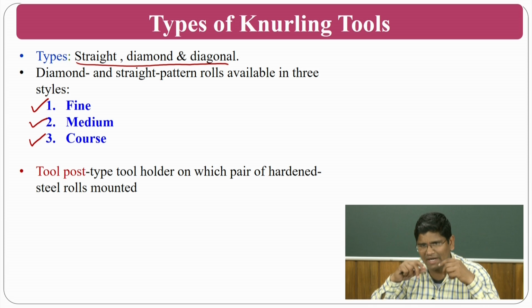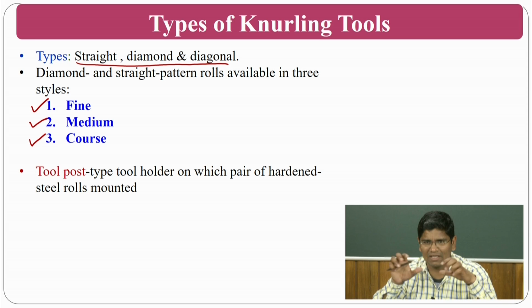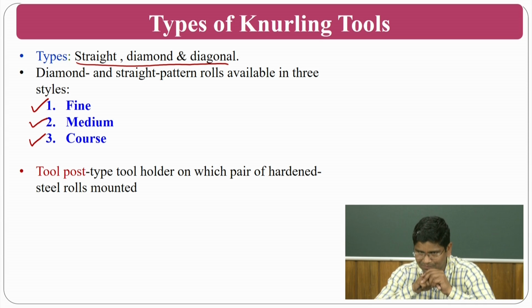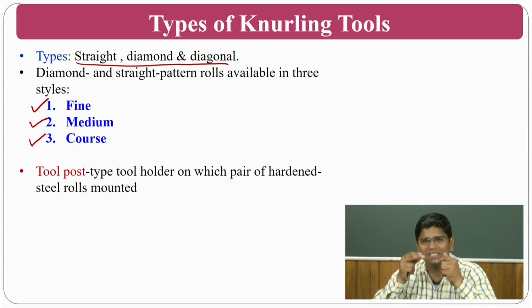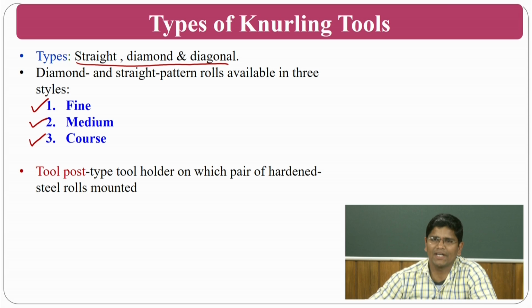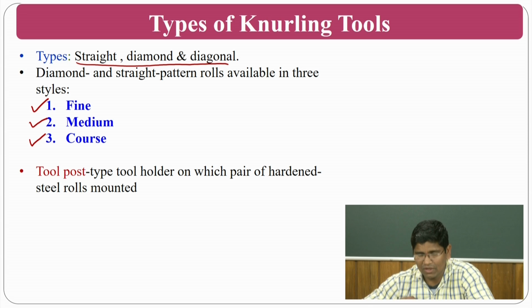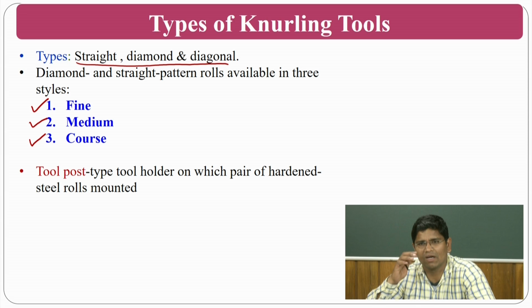The same rod you can take on the other side, if you just rotate it on the headstock, the normal surface is there, you just do the turning operation and you may experience the forces difference. So you need to study more and more from the point of temperature, forces, surface morphology and all those things. Okay, these applications are very good from the point of biomedical applications, where if I want to machine titanium or some type of materials, the temperature should not go very high, because titanium is not a good conductor, so the temperature stays on the surface itself.